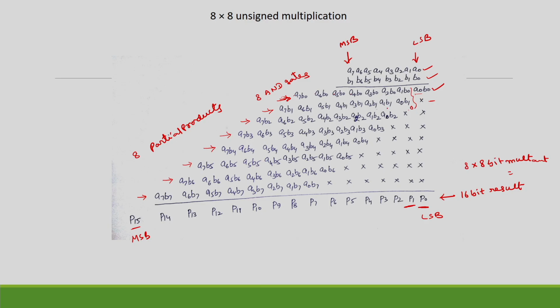Then to perform this, so these 3 bits are directly there, but here you may get one carry from here also. So, total 4 bits we have to add. So, we require one full adder, one half adder, but to have the uniformity again I will use all full adders only. If it requires only 2 bits, third bit I will make as 0. Okay. So, this table is shown in the next slide.